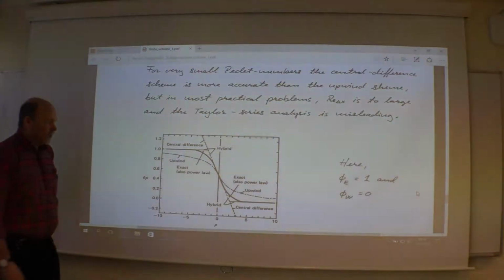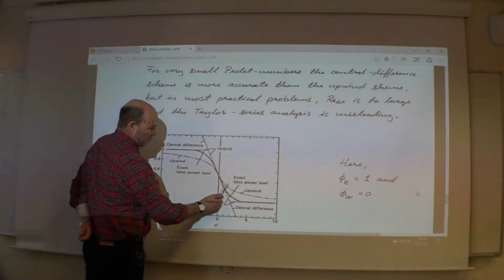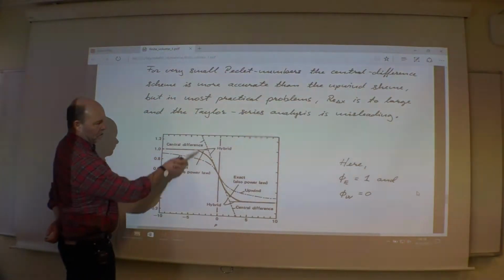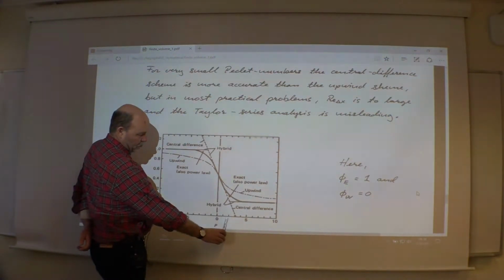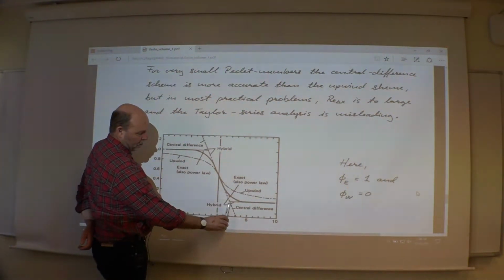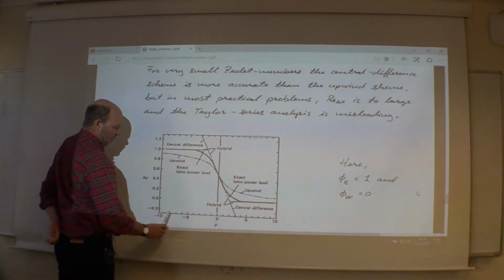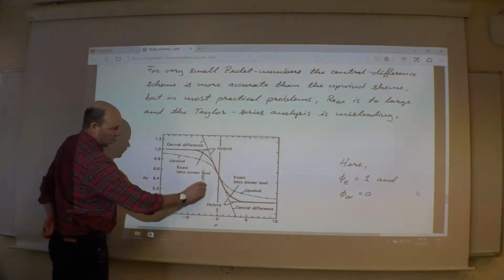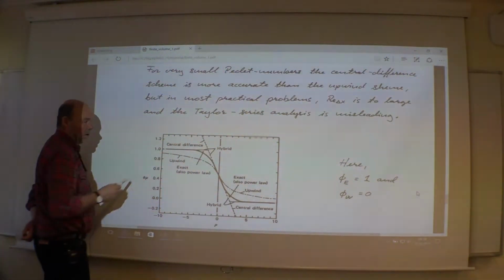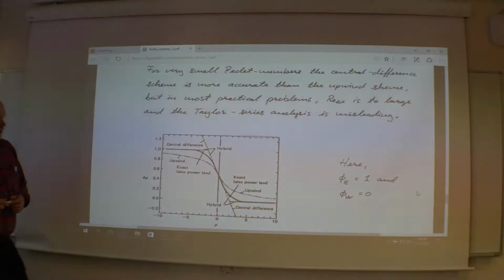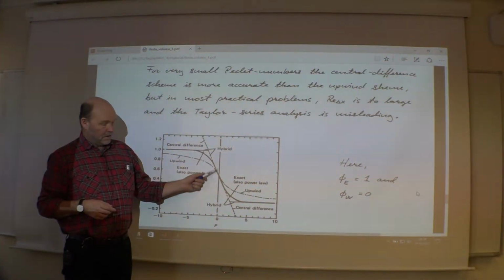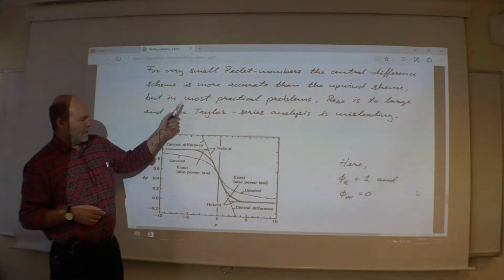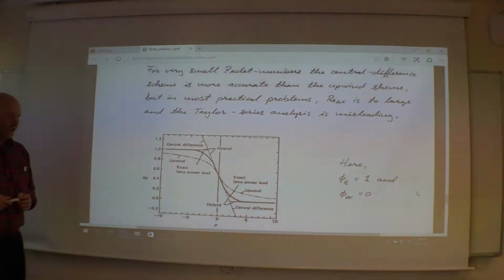The first order upwind scheme smears it out. The central scheme goes something like this. As soon as you go outside 2, you start getting negative values here, and on the other side of 2, you get values bigger than 1. Then it is outside the bounded region where it should be.